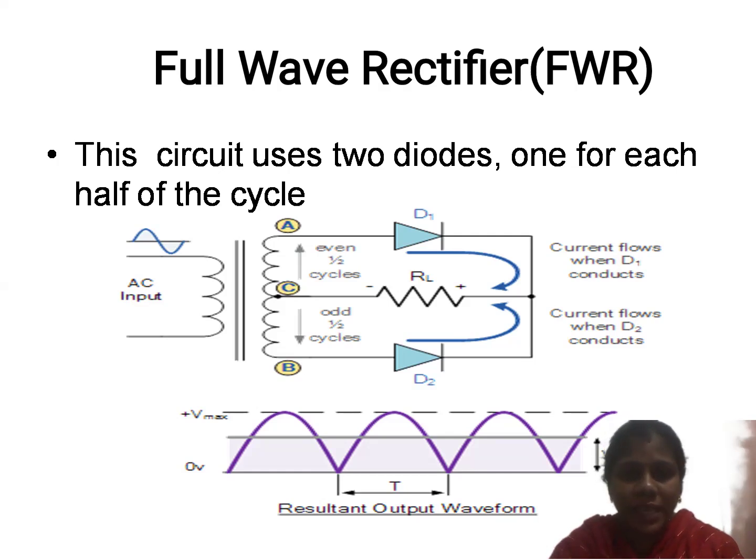So during the positive half cycle, diode D1 conducts and diode D2 is in the non-conducting state. The current flows only through diode D1, and the output voltage across RL is equal to the input, that is V0 equals Vs. And similarly, coming to the negative cycle.